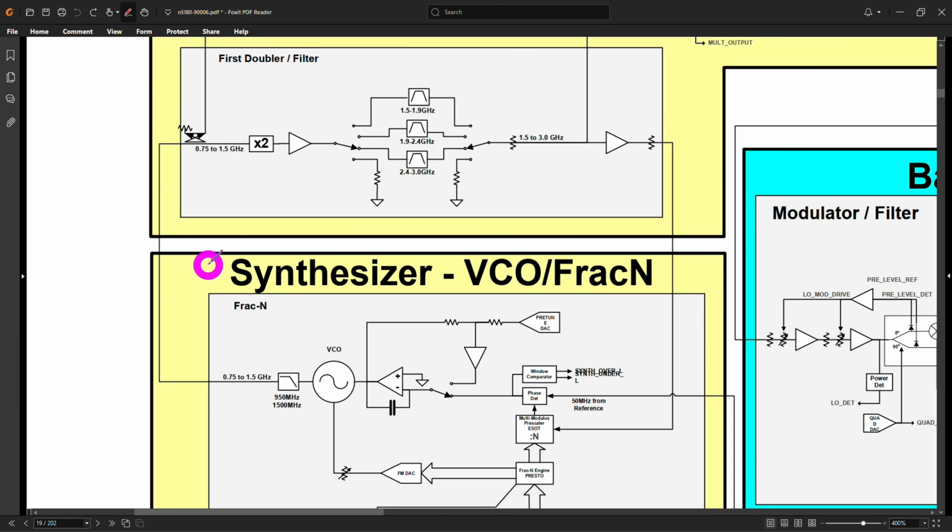So let's think about the significance of the measurement we just did. So we looked at the VCO output frequency here, and it looked just fine. We also saw the coupled path, and that was okay. We measured the doubler after the amplifier. That was okay. We looked at the signal after the filter bank, and we saw that its harmonics got better. So at least this path, where we had it selected around 2 gigahertz, was functioning perfectly fine.